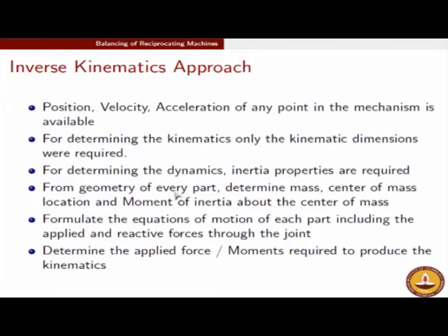In the forward dynamic approach, as you would have learnt in your engineering mechanics class, you would have given forces, and given the forces you try to find acceleration. From the acceleration you integrate to find the velocities, and from the velocities you integrate once more to find the position. But in the inverse kinematics approach, you first fix the kinematics and then determine the forces which will cause this kinematics.